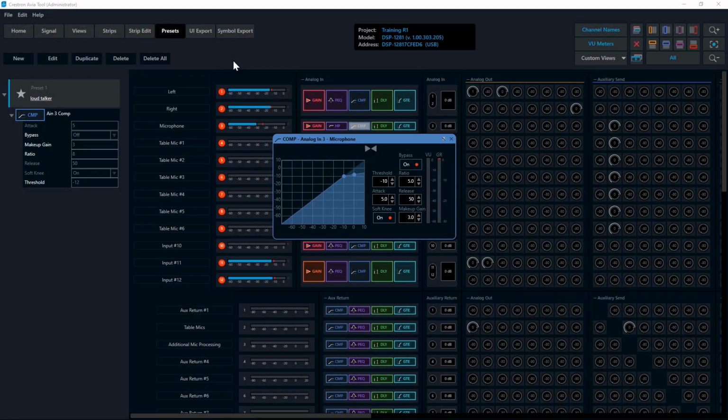Recalling a preset can be done from the DSP tool by right-clicking the preset name and left-clicking Apply. All the parameters defined in the preset will be recalled to the saved values. Note that the values in the block updated.